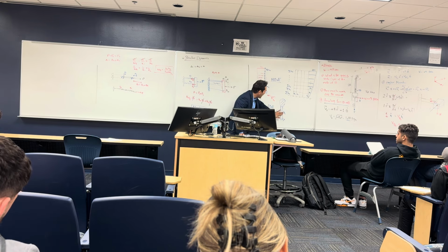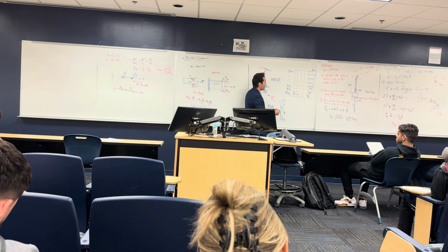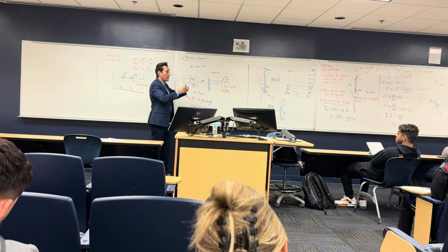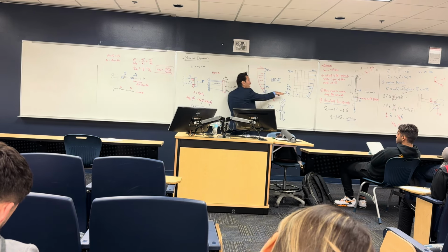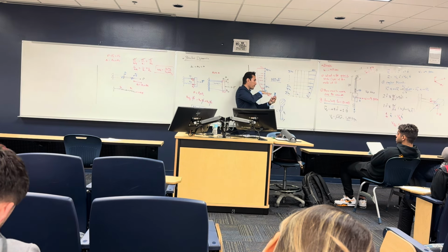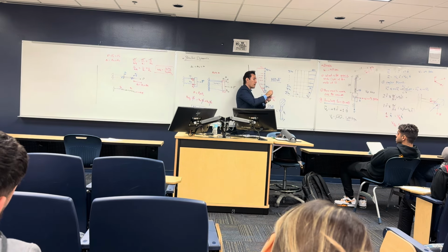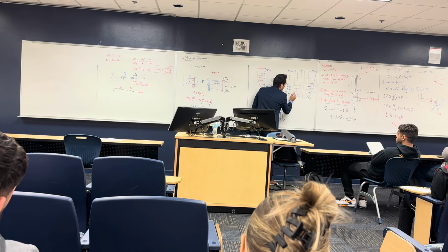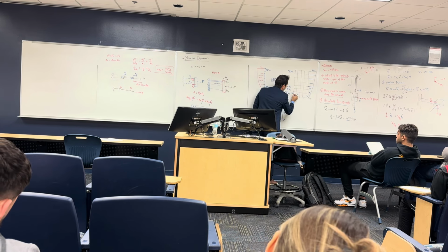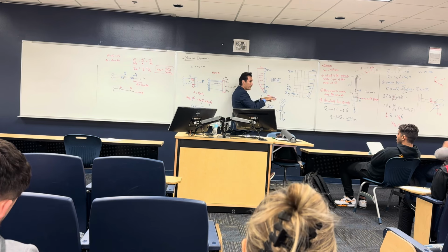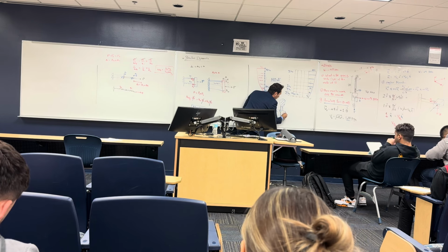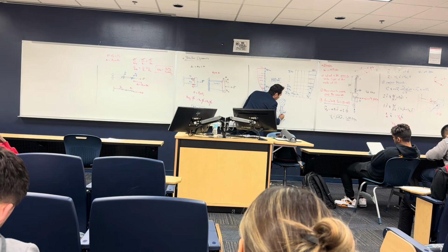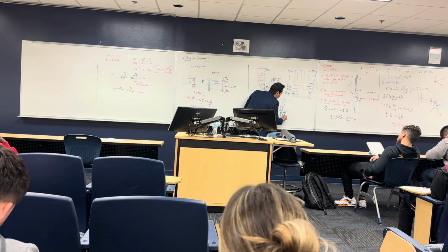And actually when we write K, this K is not axial. What I drew here is an axial stiffness, like your column in the axial direction, but what we are resisting here is shear stiffness. So if an earthquake is hitting this way, the spring should be something like this. Look, if I cut here, I should make the spring something like this, because it's a shear stiffness. Same way, if I did it here, it should be something like this. So this is K, and this is C.